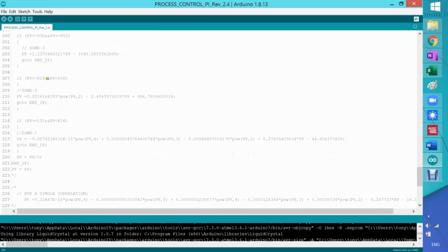How about if the ADC number coming from the Arduino doesn't fall in any of the zones? It means I probably have an overflow or something weird going on, like I'm in the extremes of the range that I can use. So I use this concept of dividing by 0 here, just for the fun of it. That will cause some trouble, so you will know that you are totally out of spec within the range. No problem.